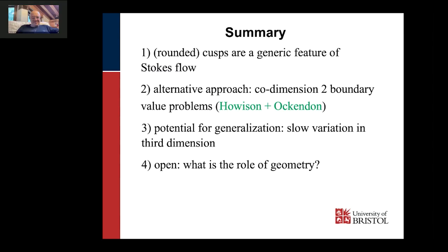Yeah, if I comment on that, surely the answer, Jens, is that viscosity does enter into the definition of capillary number as well. And the radius of curvature at the tip depends very critically, exponentially in fact, on the capillary number.